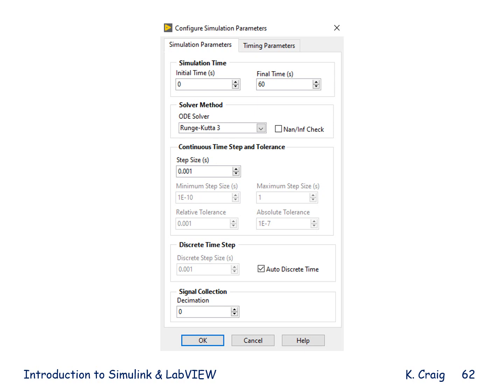In this control and simulation loop, we configure simulation parameters. Here, the simulation parameters we need to focus on are the initial time and the final time. I'll be running my simulation for 60 seconds. I can pick an ordinary differential equation solver, and I choose to pick this one as it is a fixed step solver.